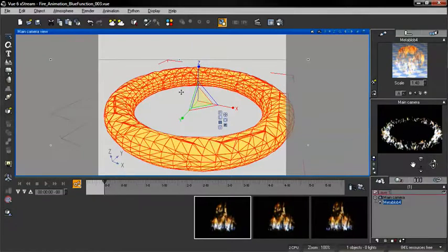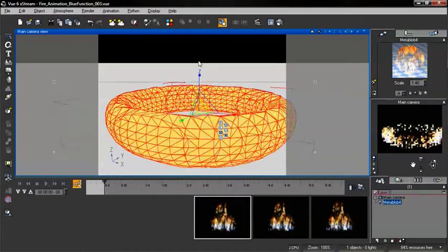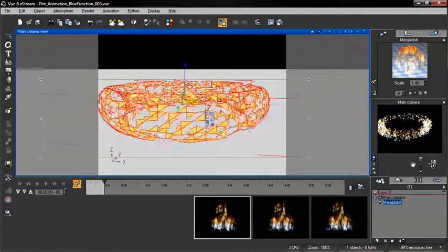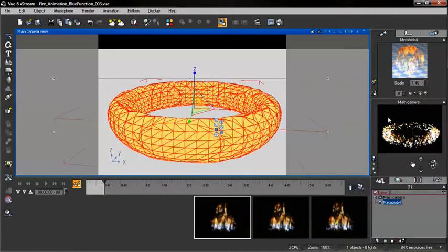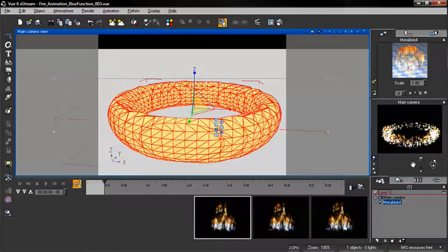And we can also see, because of the overall shape of this object, that we're seeing much more of our blue flame, and that's directly related to the fact that we were using slope to control our blue flame. So we can stretch this upwards a little more, and that would reduce it, and then we can see more of our yellow flame. And then we could also fill that value in, and just fill in our shape a little bit more by reducing our fuzziness. And now we can see more dense flames, a lot more of them.